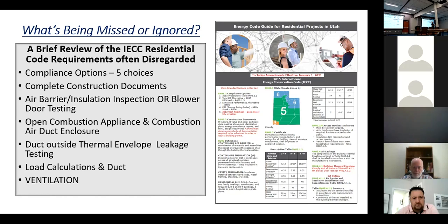And then we put a duct in the attic and the air conditioner's running. And a lot of code officials, building inspectors say, well, we don't want to disturb the thickness of the insulation in the attic. So they make them suspend the duct up above the insulation. They do. I know it's crazy. And you're just going, oh my hell. But it's insulated to what? R8.